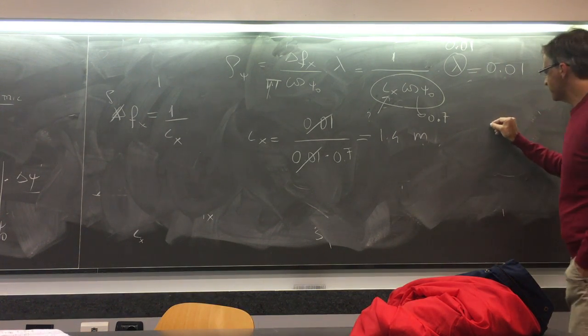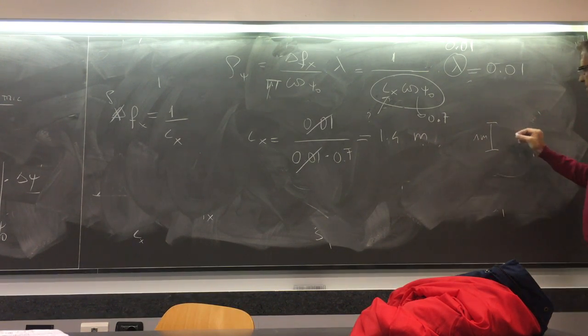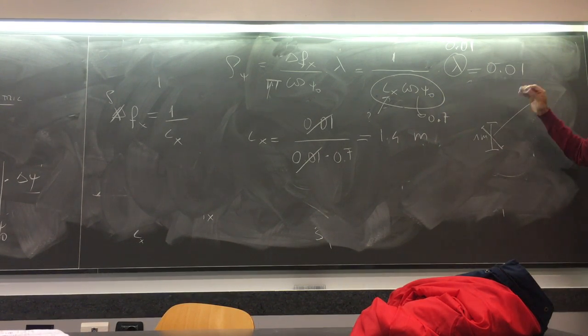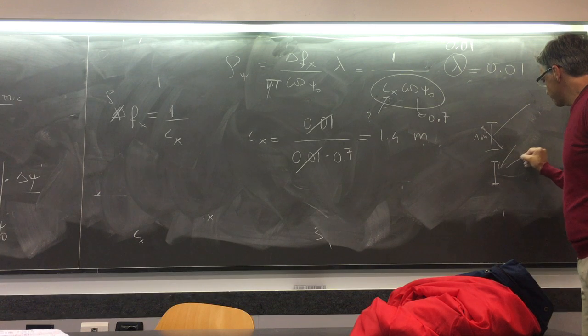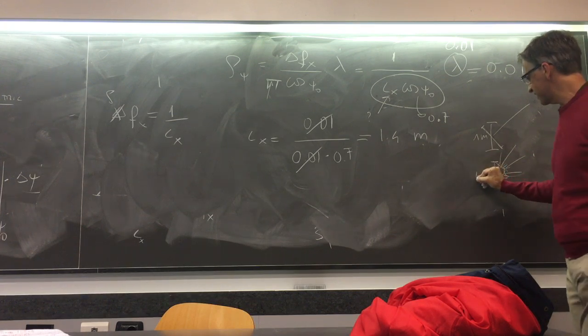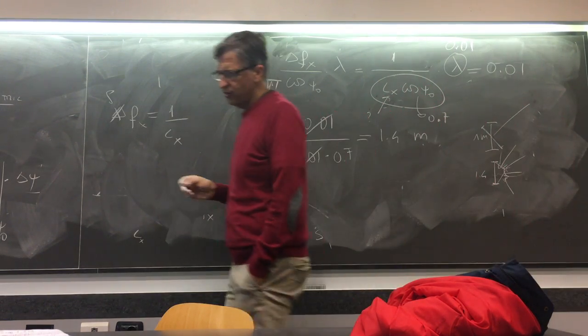So you remember, if you have the real antenna, you can have it with 1 meter, okay? But the point is that if you rotate the real antenna, it is always 1 meter orthogonal. If you have the array, since you don't move the array at all, you use this trick to do simultaneous beam forming in all the directions. So you simultaneously point your antenna with a sort of trick, but now your resolution is wider, and you must compensate by making the antenna a little longer. That is 1.4 meters. That is not so much, so you get a lot.